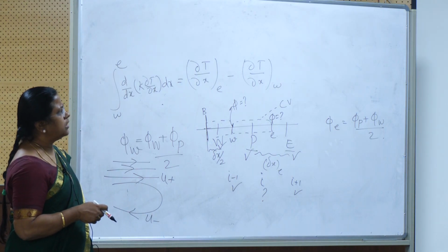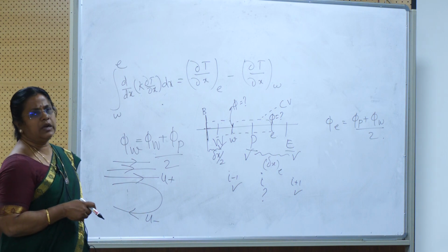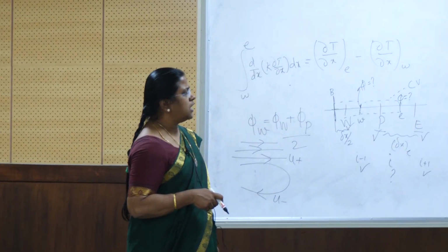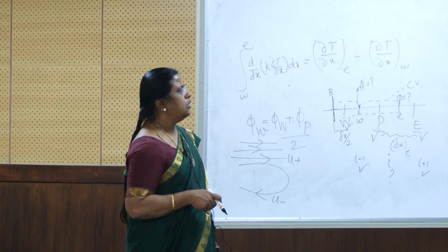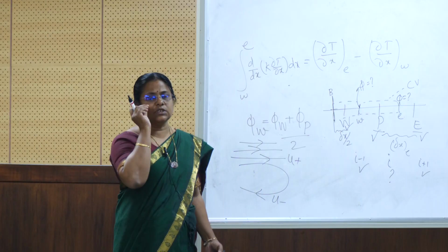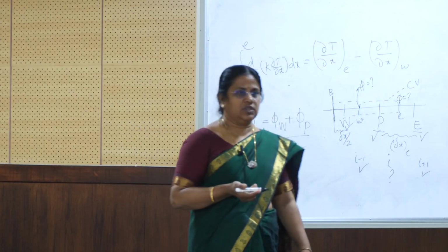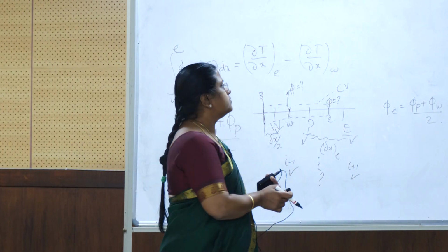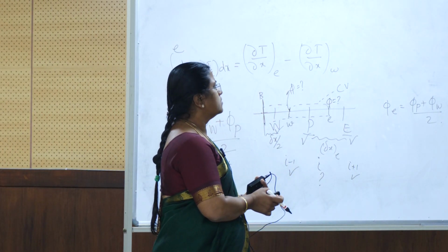Now he is giving these names for this. AE, AP, AW are there. It is written in terms of D and F, the coefficients, combination. Okay. Since by continuity FE equals FW. Why? Because the divergence of the velocity vector is 0. Already we have seen that in the continuity equation.